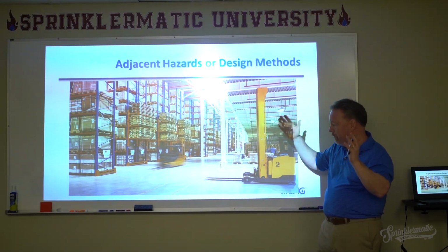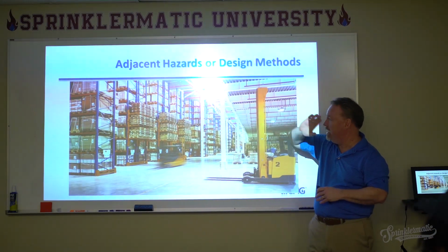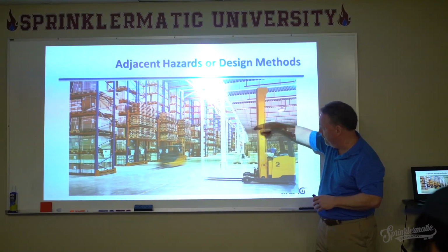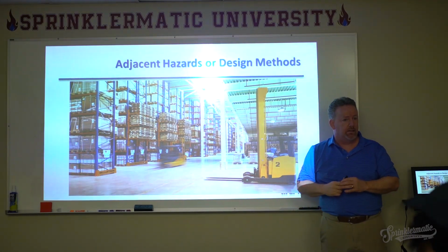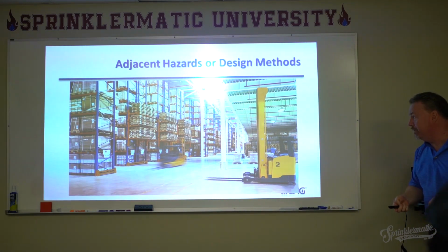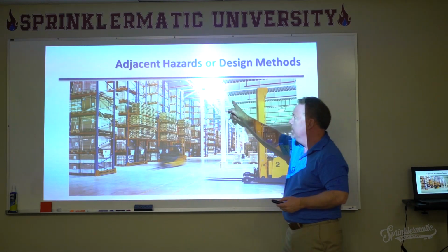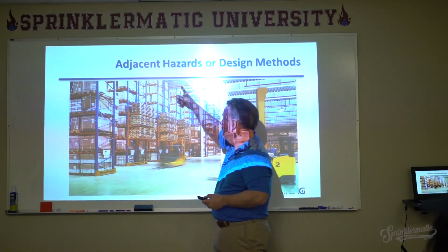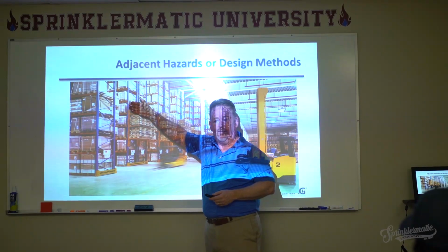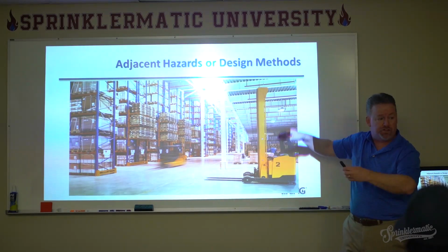All right, so we've got a requirement for a separation here, an aisle separation, and a draft curtain, or a separation in the ceiling height. And then we can have these two design areas close to each other. And that's the only time you can use draft curtains. You couldn't use draft curtains if this is an ESFR sprinkler system out here, which most likely it is. You can't have draft curtains within this design area, but you could have a draft curtain separating the two design areas.